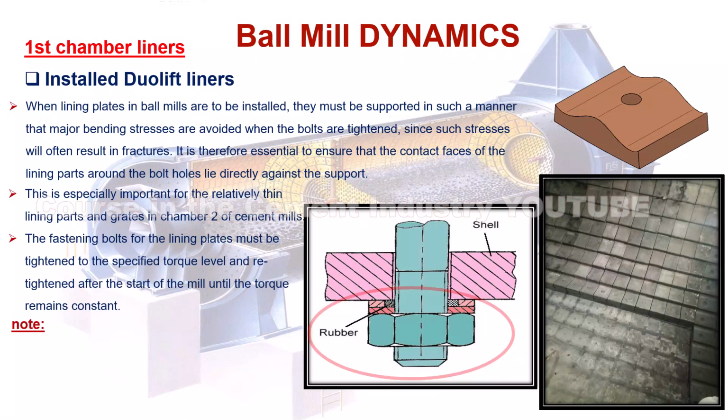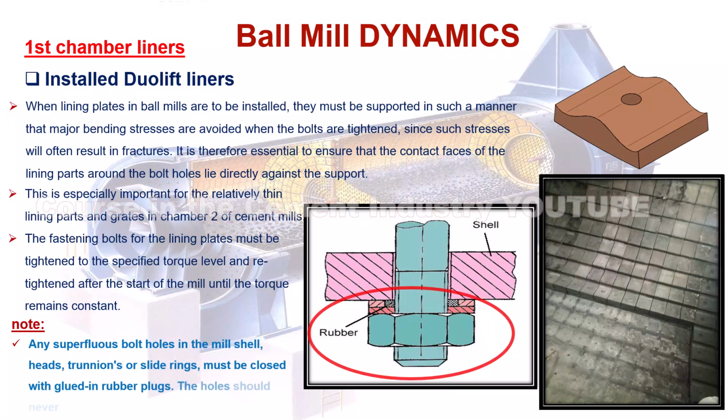Note: any superfluous bolt holes in the mill shell, heads, trunnions or slide rings must be closed with glued-in rubber plugs. The holes should never be closed by welding.